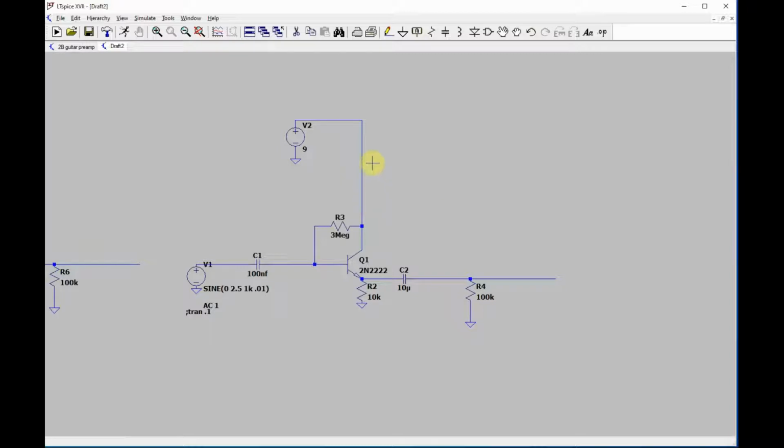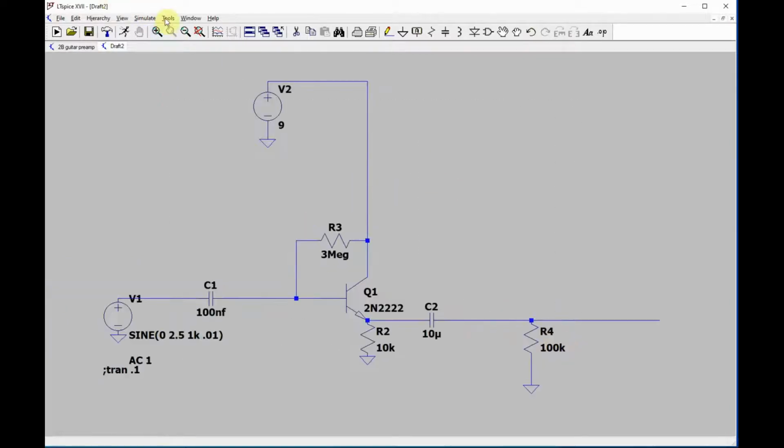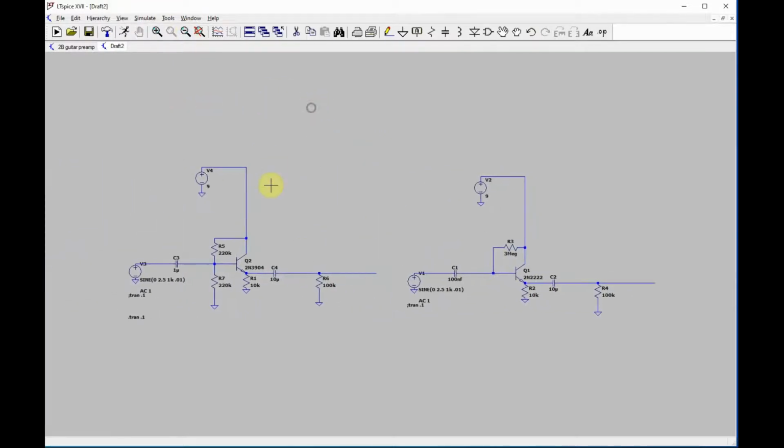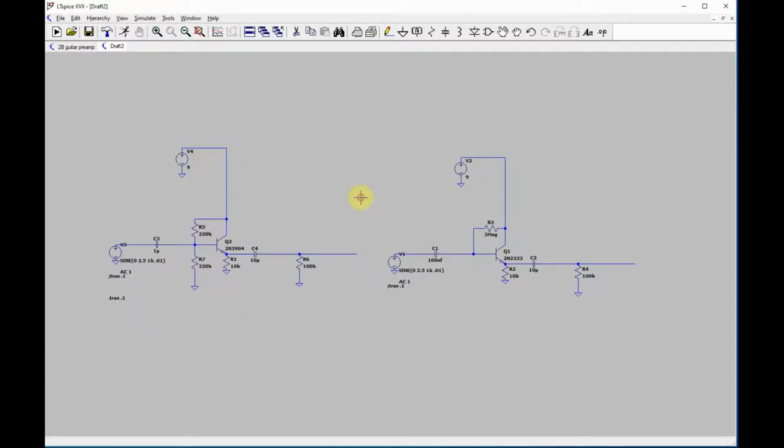And there's also an easy way to check here too. When you have this hooked up, if you want to say, well, boy, did I get a bad transistor, maybe you've already soldered it in, you're not even sure, you don't even need an oscilloscope. You just take a multimeter, hook it up to ground, and put the positive here, and whatever voltage you read, that's the bias. I hate to make things too complicated, because this functions so much better than this almost all the time, and I've never had a problem with it. And actually the transistors I've used have been fairly uniform.